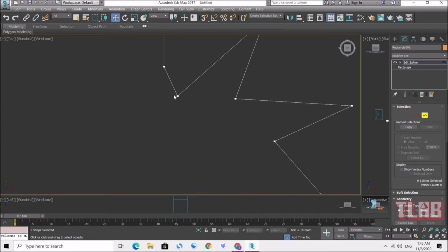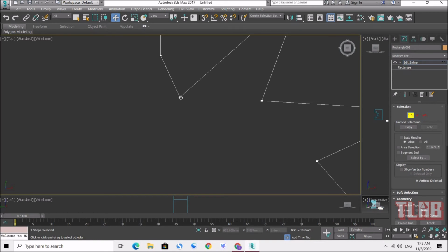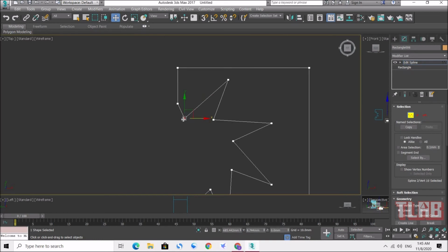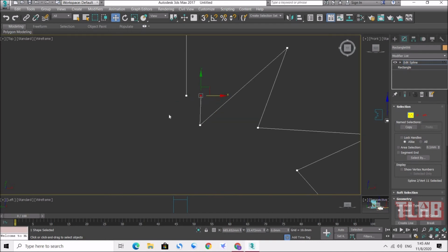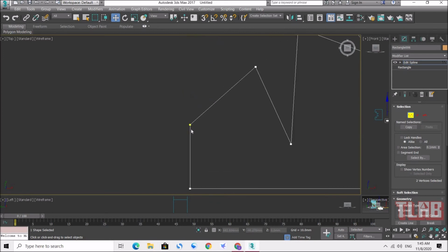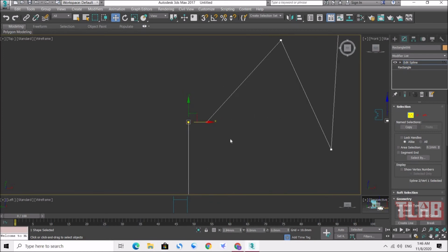But like you can see, if now I select the vertex, I click the vertex, click the point, and then you tap up. Oh, not here. Okay, this one, you tap up, you see, actually there are 2 points in the same place. So that means these two you need to combine together. Including this one, you see, it has 2 points. So you need to use Weld to make them become 1 point.